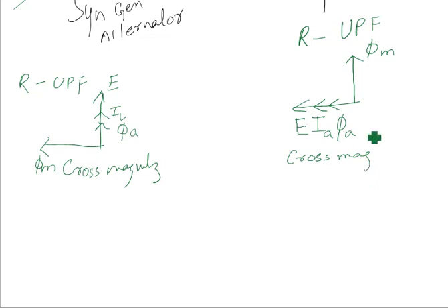Okay, so this is how things go on. Now let us see what happens with L load. L means zero power factor lagging, ZPF lagging. Zero power factor means power factor will be zero, means phi is 90 degrees. So power factor is cos 90, which will be zero. That is why for inductive load we term it as zero power factor lagging load.